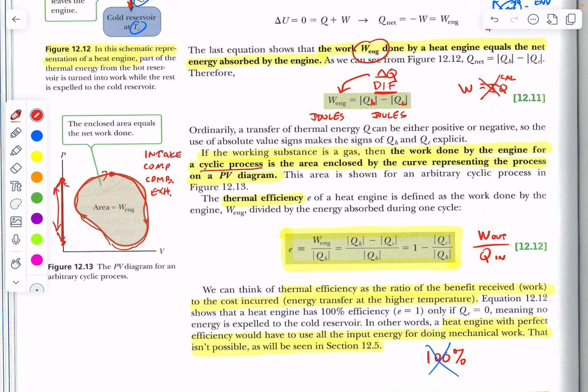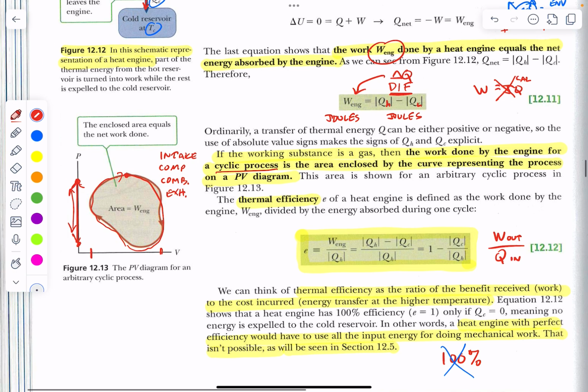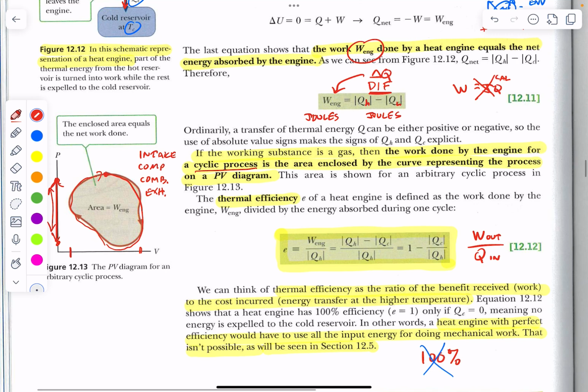And in the process inside your cylinder, you begin with a cylinder wide open before the piston compresses the gas, and then the piston compresses the air-gas mixture, and now you're at a small volume, and then the explosion pushes the piston back out again, and now you're at a high volume. And as we've said in previous screencasts, the area bounded by your diagram represents the amount of work that is done by this engine in this theoretical cyclical process.